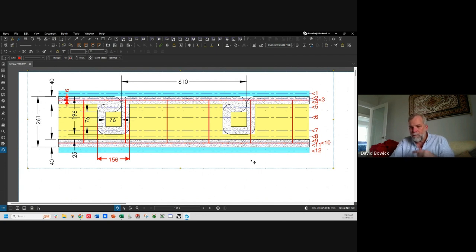So the way we evaluate the R value of a wall is we slice each different plane, calculate the effective R value of that plane, and then add them all up, and that gives us the effective R value of our system. Remember that when planes are in series, we add the R value. When planes are parallel to the direction of flow, we add the U value, we add the conductivity.